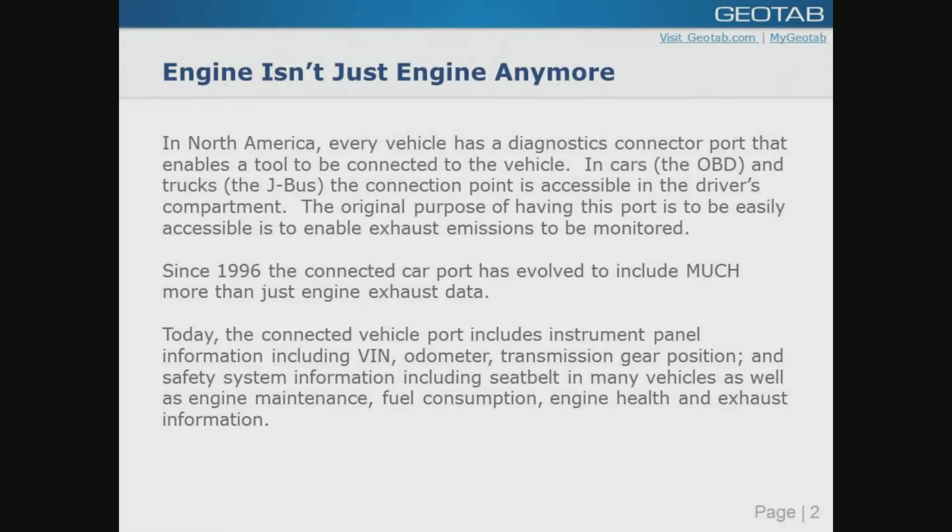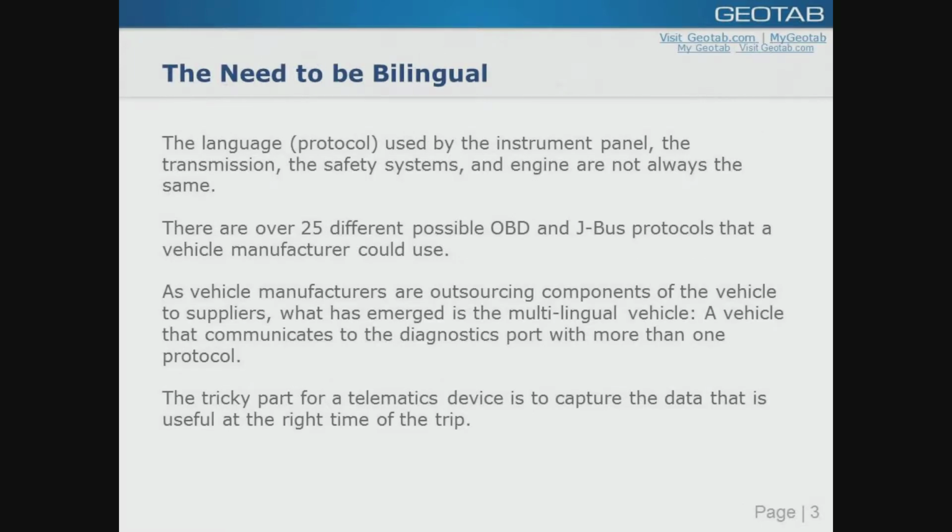It's important to understand that while there is an OBD plug in every vehicle, all vehicles do not speak the same language, also known as the protocol. There's actually something called the Society of Automotive Engineers, SAE, that defines how set pieces of data must come off the vehicle. So you've got regular data that is regulated, that's your emissions and your fault codes and that kind of thing, and then you've got other sets of data called proprietary data.